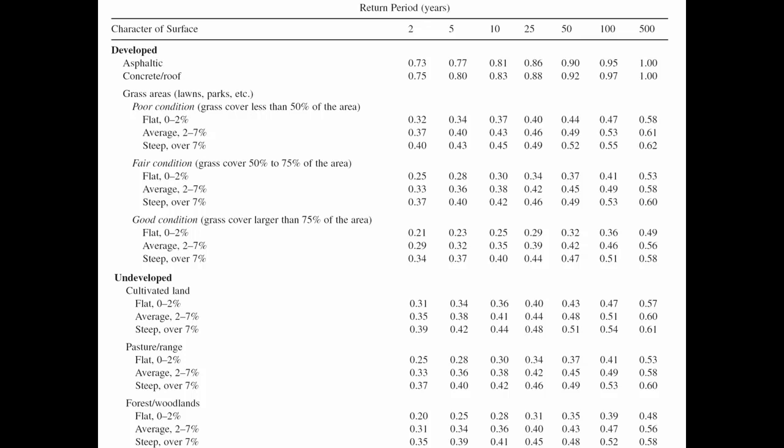Now, I'm just guessing that the rail yard has a C value of 0.6. And what is that based on? Well, let's say maybe it's partly dirt, partly rocks, you know, the ballast that they have near the rail lines itself. On the one end, if it was all concrete or roof, it would be 0.8. So it's not that bad, but it's not grass either. It's not even as good as a poor grass. And so this 0.6 is just, you can call it a guess. If we wanted to put a nice spin on it, we could call it engineering judgment.